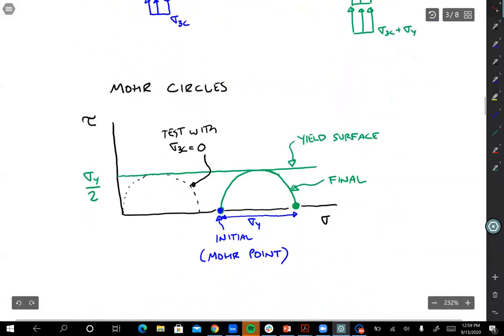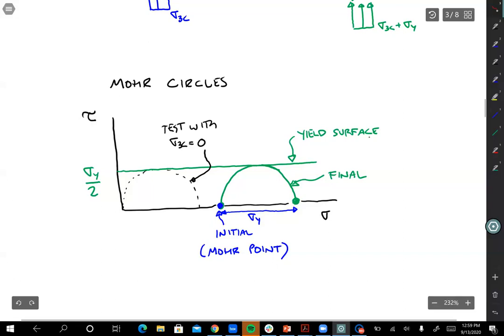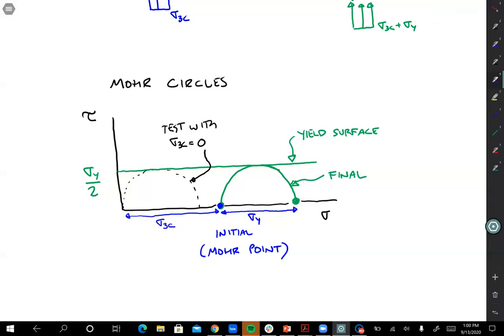All right, now let's talk about the Mohr circles. So first, we have the initial condition, and this value is equal to sigma 3c. So let me label that stress value so it's clear. Draw a line here, like that. So initially, we have a point. Maybe I'll erase this one. So initially, we have this blue circle right there. And since the stress is the same in all directions, there's no diameter to the Mohr circle. There's just a point, right? It's an isotropic stress tensor.